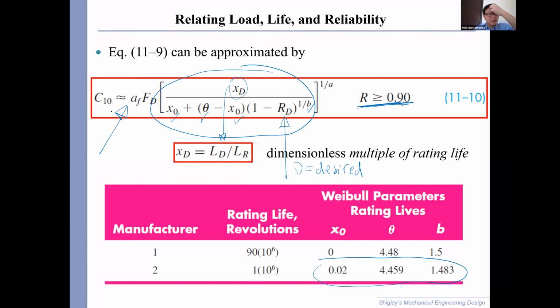Remember, stress concentration is a multiplication to make things worse than they are. Let's say you're doing this bearing for a sand pump for mining, then you have a lot of impact, right? That's your application factor. It multiplies the load so that it's worse than normal.